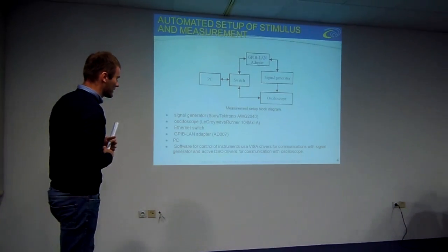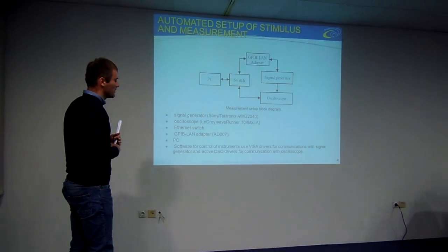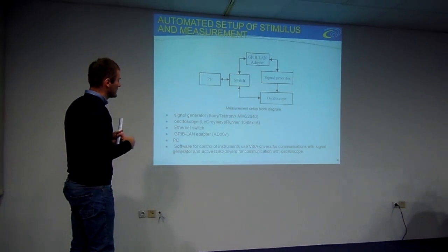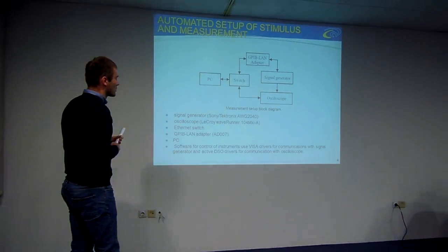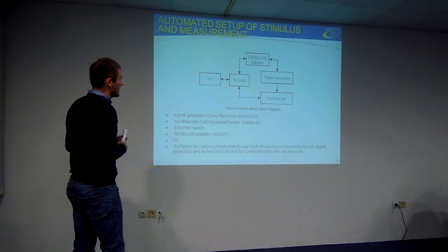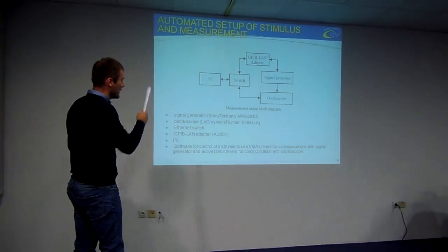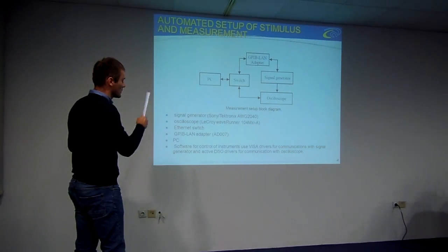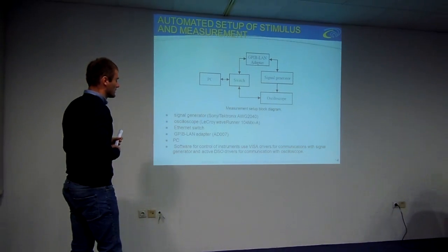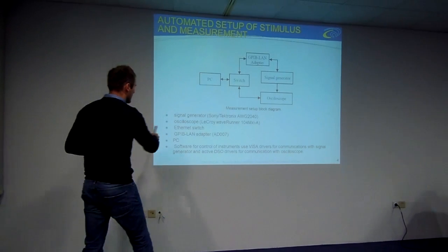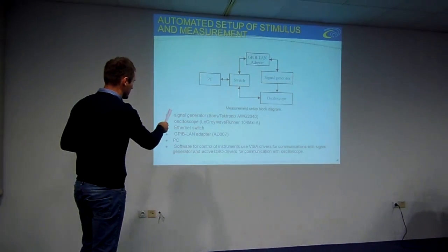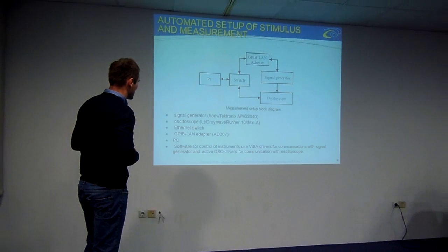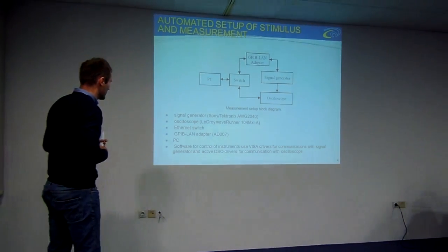Our setup for that purpose is simple. We have a computer with a switch which controls the signal generator via GPIB LAN, and the switch is connected with Ethernet to the oscilloscope. We have a Tektronix signal generator and a LeCroy oscilloscope.